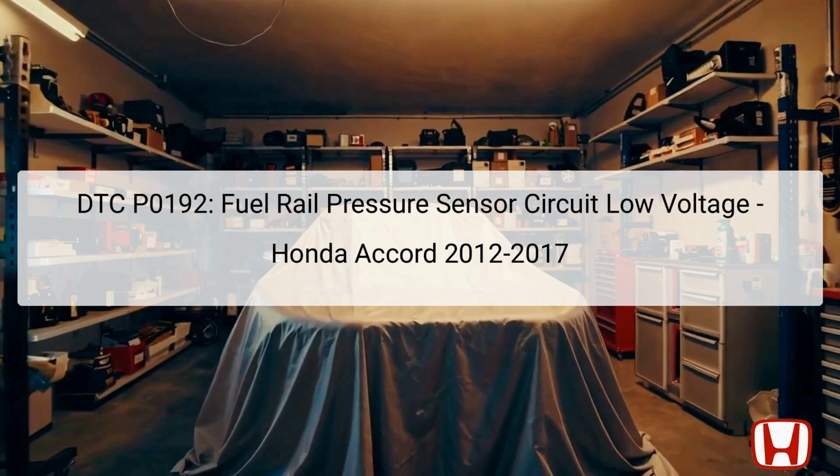The fuel rail pressure sensor is designed to sense the fuel pressure in the rail and convert that measurement into electrical signals that inform the powertrain control module, or PCM, about the current fuel pressure status. This information is vital for the PCM, as it adjusts the operation of the high-pressure fuel pump solenoid to maintain optimal fuel pressure. If the sensor's output voltage remains outside of its designated range, it prompts the PCM to detect a fault and store this DTC.